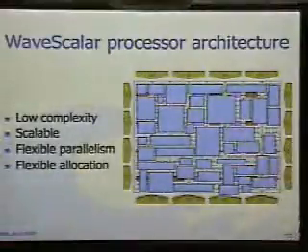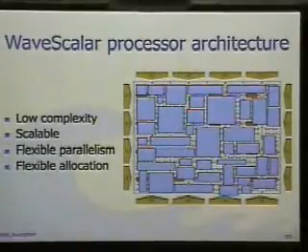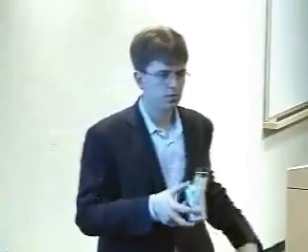So I'd like to rephrase that question I asked earlier that was sort of silly. When I asked about the associativity of the cache, I realized that now I understand it's 64-way associative and that you might have 64 instructions in the same PE. But the downside is if a bunch of instructions do gang up on that one PE, unlike an instruction cache where there's no cost to that, here you're splitting the compute time of that PE. I'm saying if the compiler assigns 1,000 instructions to one PE, and then it turns out you need all of them active at once. Well, that would be true on a 64-way set associative instruction cache as well.